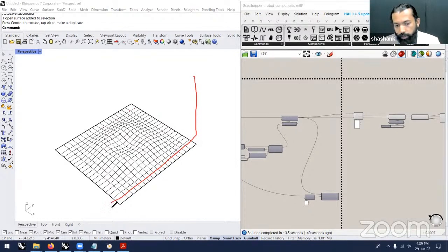If you were to not create an out point, then what is going to happen is that after it reaches the final point over here, it is going to go back in the fastest way to the second point, and this we don't need. So what is the ideal path? After its first pass along the first line, it needs to clear the model. So you will create an out point, maybe in the Z direction if it is perpendicular, so that the tool moves from here. This is the tool. It comes here, it goes all this way, and it exits. So that is why we are creating this exit point.